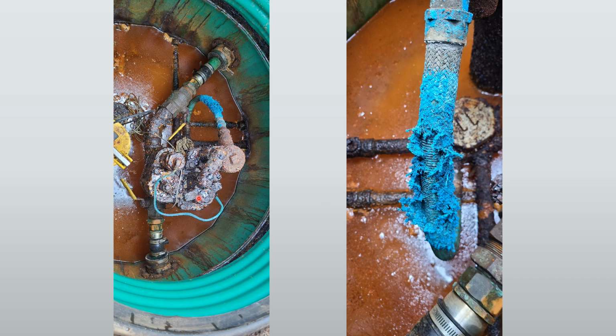And this is just another overall example of what the turbine sump environment looked like, and then a close-up of that. But one proposition too: maybe flood turbine enclosures and put a galvanic anode on the inside. You can't have an effective anode without electrolyte, but if you can flood it, you can have CP. So I don't know, maybe something to consider for the future.